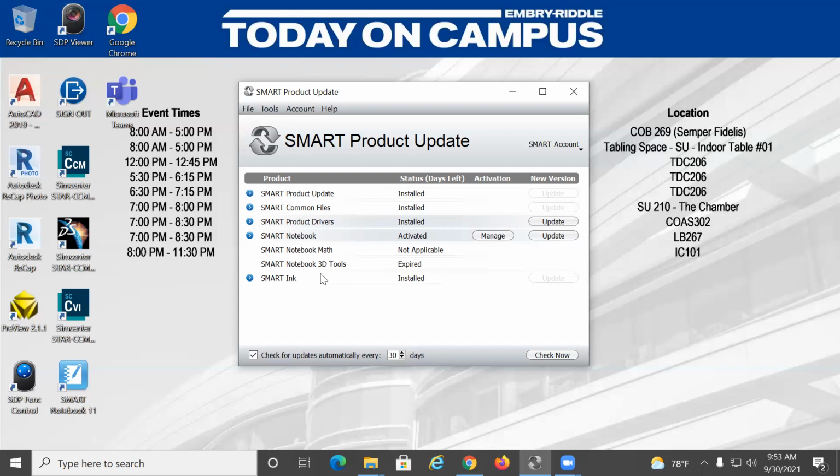It is fixed at the left end. It has a rectangular cross section, and the cross section is 6 inches by 12 inches. And of course, it is going to be loaded about its strong axis. So this is the reason I'm showing my rectangular section oriented vertically.